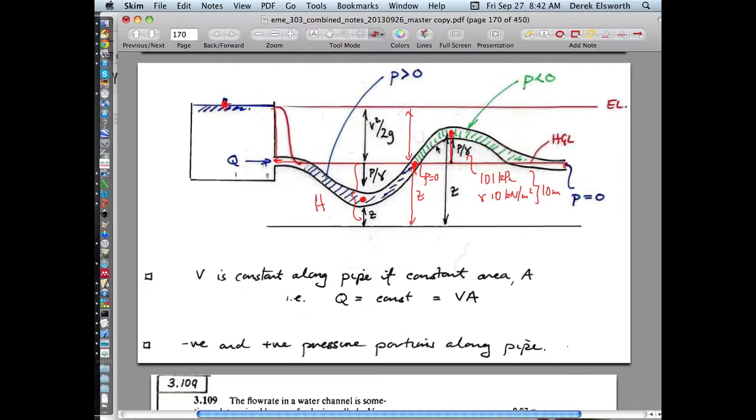So that's why if you take a 10-meter tube and you suck on it, you won't be able to get water out. You can't suck water out of a well more than 10 meters at a time, water, and oil for that matter, because all of a sudden it will cavitate. The only way you can do it is to put a pump at the bottom and physically pump it up by pushing it, so you compress it from the bottom. And so it's another exposition of the fact that you'd expect the fluid pressure here to be negative and it would cavitate. So you'd gather bubbles in this particular case.